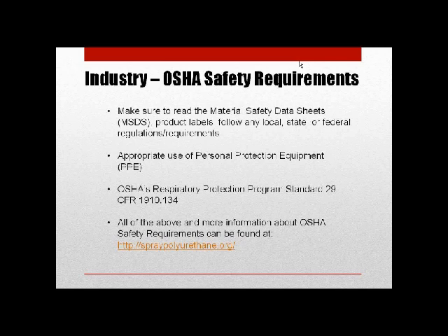Okay, you have the appropriate use of PPE, which is short for personal protection equipment. Proper instruction must be given in the use of PPE to make sure that the applicators and helpers are properly protected. Next, we have OSHA's Respiratory Protection Program standard. The respiratory program is an absolute must when a contractor is requiring their personnel to wear a respirator to spray foam. And all of these items, OSHA's safety requirements, can be found on spraypolyurethane.org. It's a very informative industry safety website.